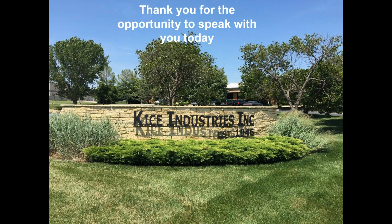But again, in most applications, you're not going to see a noticeable difference in bag life, maybe weeks, but definitely not months or years versus a 12 ounce or a 16 ounce filter bag. But again, to go back to the original question, the type of filter media as far as fabric weight does not affect how we figure air to cloth ratio.